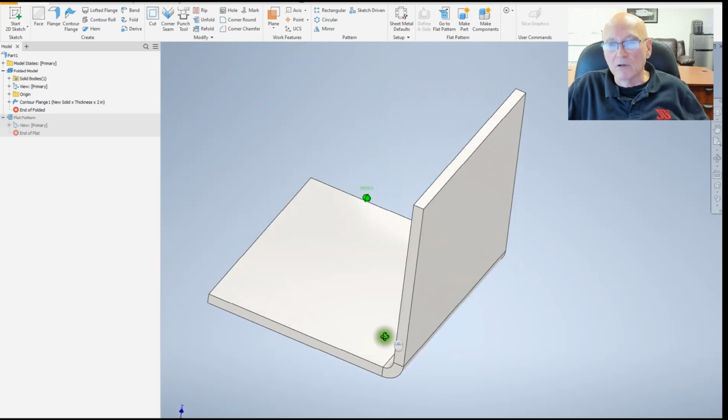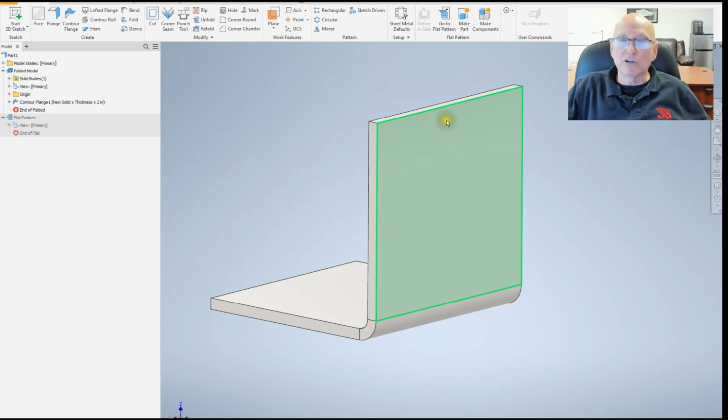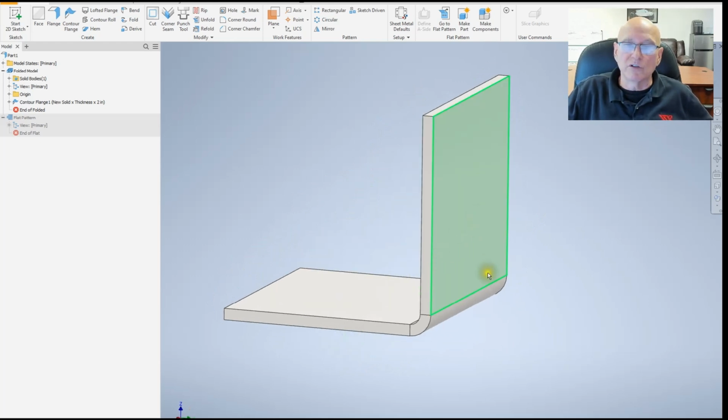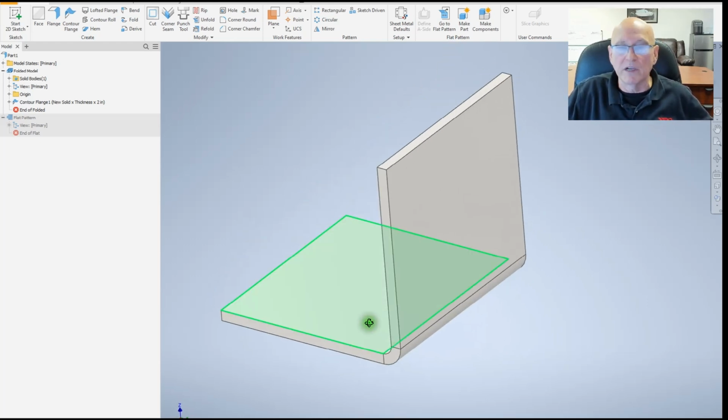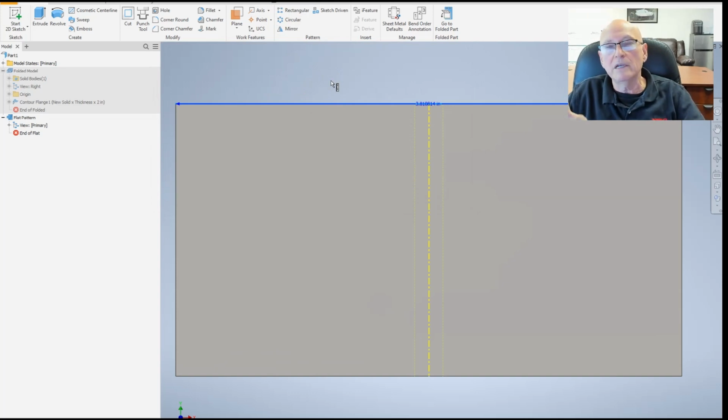We have a piece of metal here that should be 2 inches tall, 2 inches wide. We measured it at 2.1 inches tall by 2.1 inches wide, so we're 200 thousandths of an inch too wide. If we go to our flat pattern and measure, I'm sorry, hit the wrong button. We measure here, we get 3.81. We need to change that number, because if we're at 2.1, this particular number here is going to have to get smaller if we want to get to the right deal.